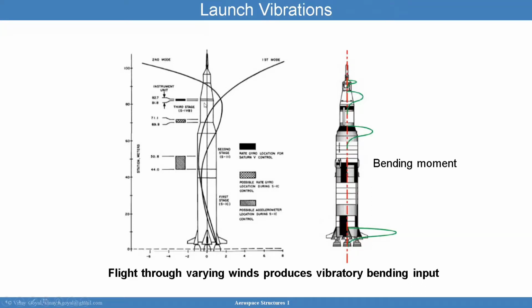Here in this picture, you can see the loads acting on this launch vehicle. You can see the first mode here and the second mode here as an example. I'll presume that you have high loads here in this location. Anytime you have high curvature in the deflections, you're going to see high bending moments. So this deflection diagram, if you take the second derivative of it, will show you where the highest bending moments typically are. But those can be calculated directly through a free body diagram and, more precisely, a coupled loads analysis. That will be much more precise.